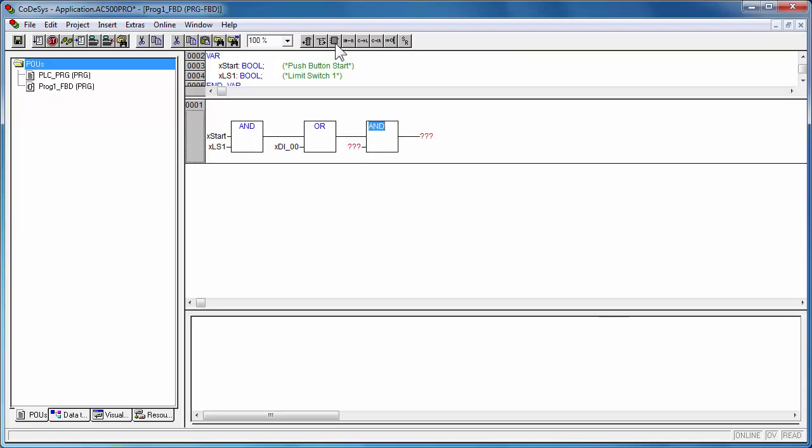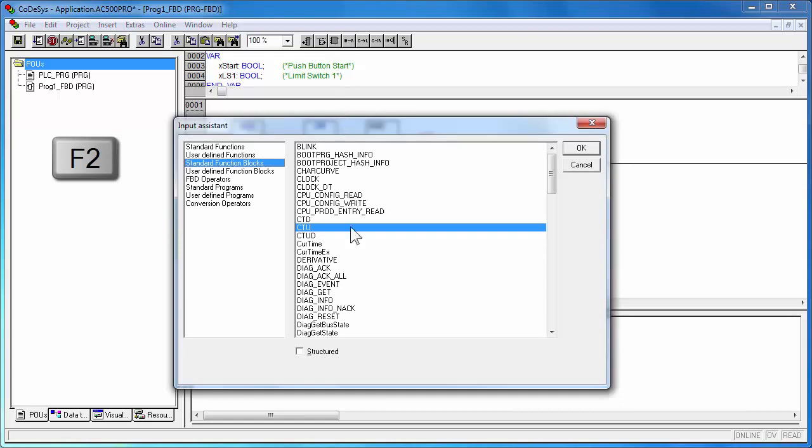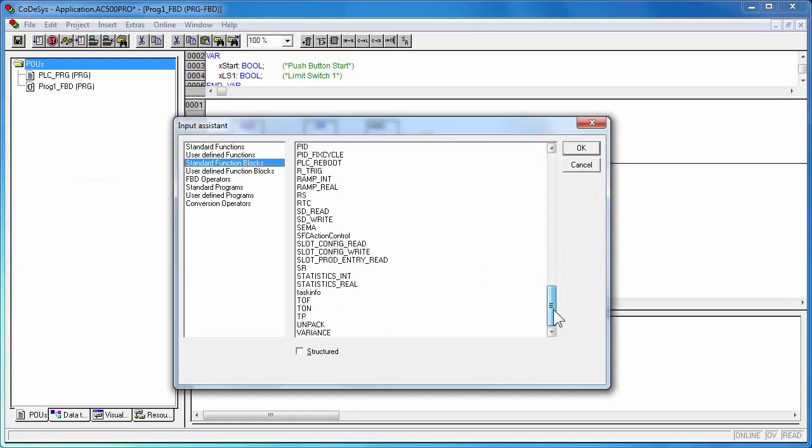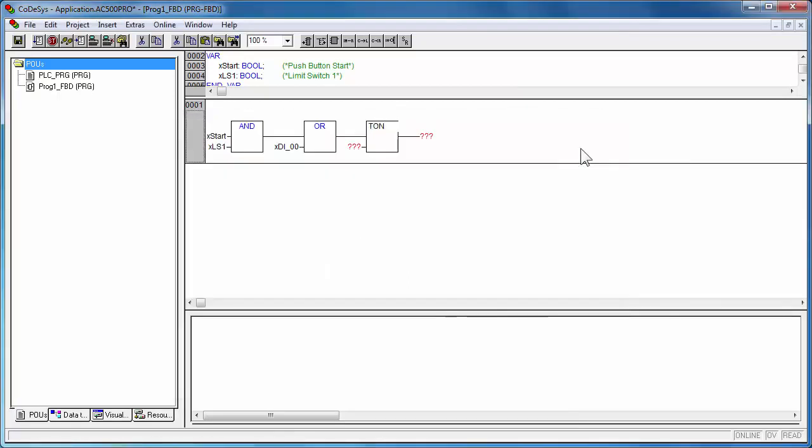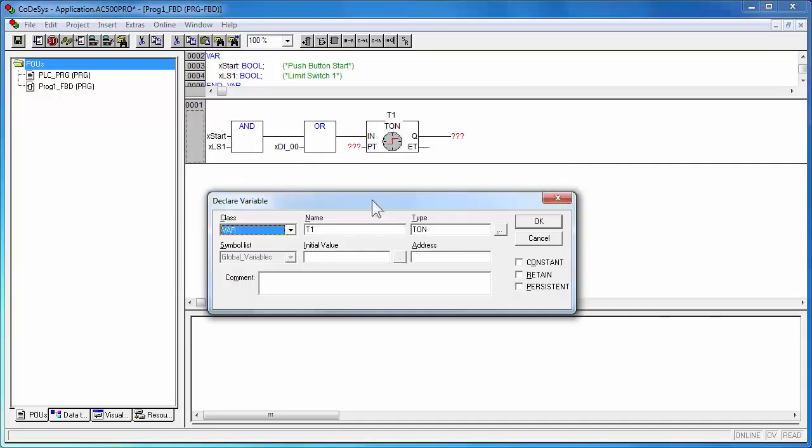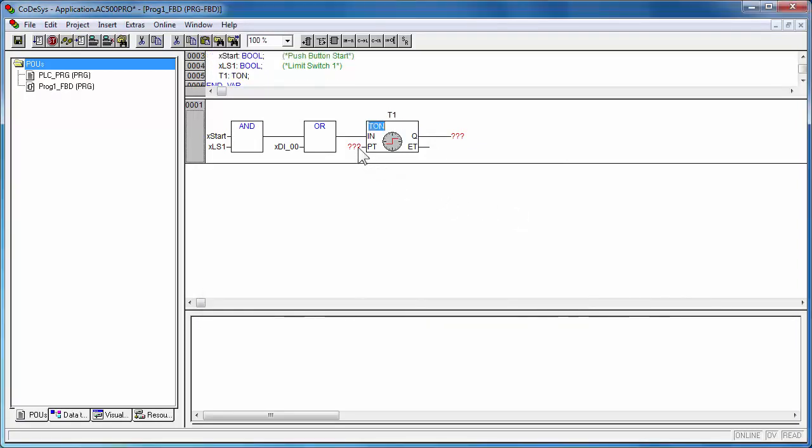Likewise, a timer function block TON could be programmed with appropriate input-output parameters. The preset time of timer can be a constant time. The value must be in milliseconds, seconds, minutes, hours, or combination of them.